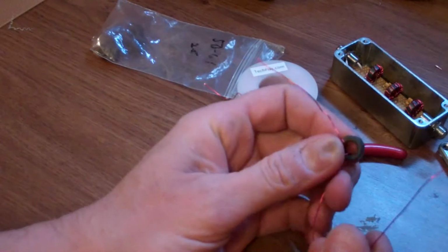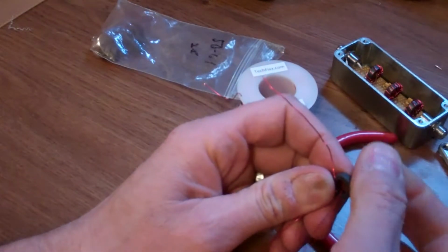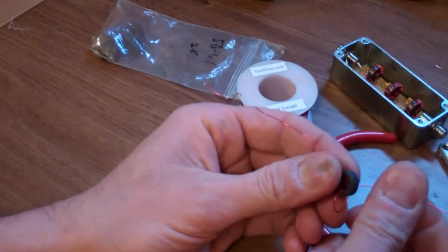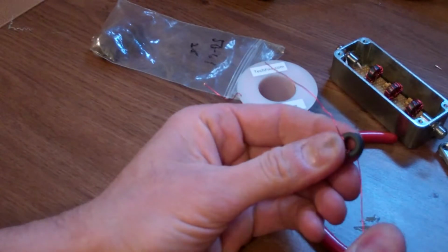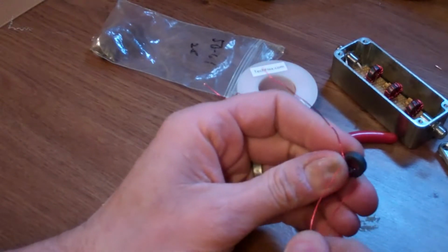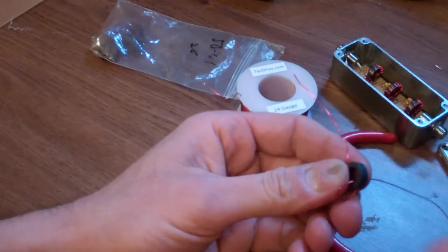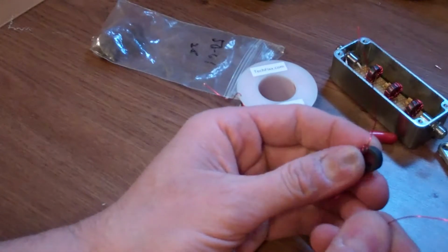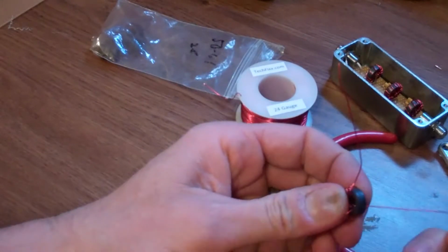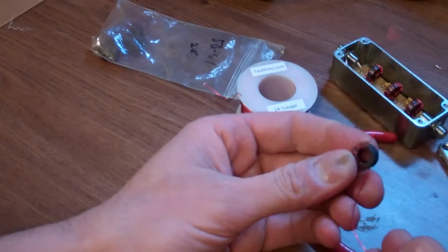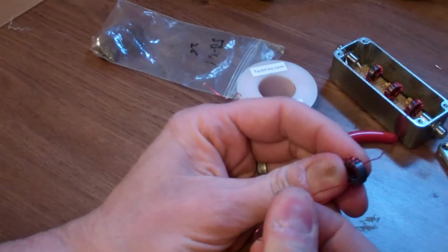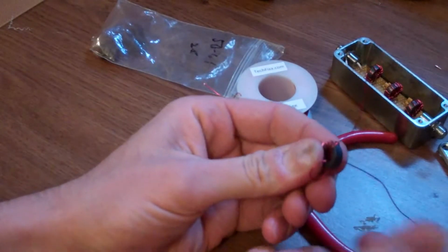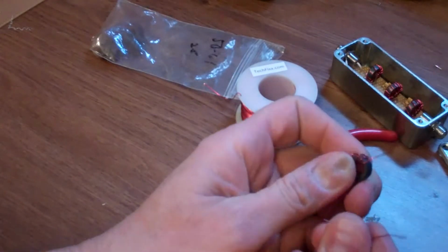If they're larger ones, you can wrap them with Teflon tape. I usually wrap the larger type 75 material ferrite toroids with some Teflon tape, so I reduce that chance of getting a short in there. But basically, you just go on. It's pretty quick. Once you do this a few times, it's a lot easier. You get the hang of it. It's very fast.